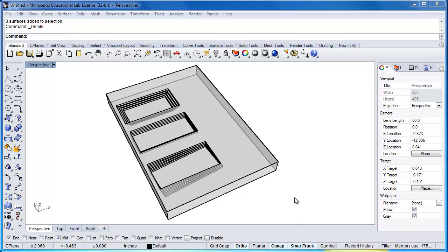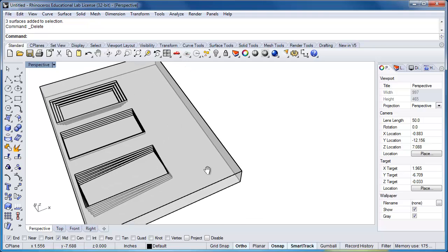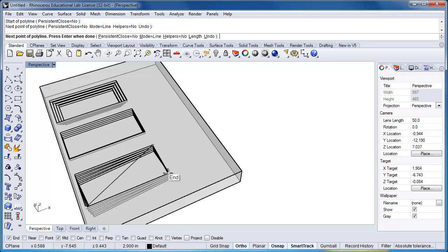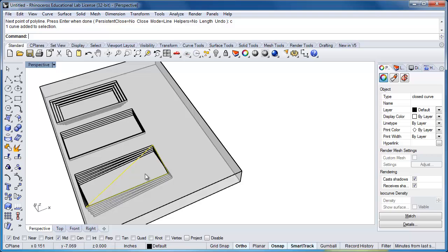So let's say off of this rectangle that I folded my pages and I folded them over in this direction and I cut them so I had a triangular shaped piece of paper over on this side. And since I know that I cut it out of this, I know that it would fit in there, so I'm just going to use the geometry that's already here to draw a closed polyline that's the right size, and then I'm going to rotate 3D to flip it over to the other side.